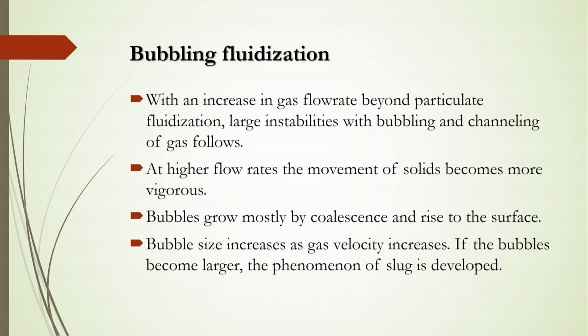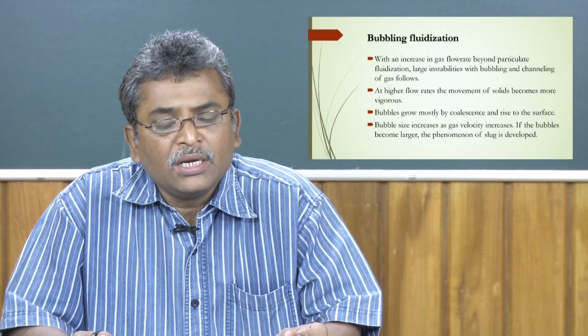Whereas in bubbling fluidization, of course, you have to increase the gas flow rate beyond this particulate fluidized bed, so that you can have large instabilities, or some instabilities, in such a way that there will be a formation of bubbles and channeling of the gas that will flow inside the bed. And at higher flow rates, of course, the movement of the solids becomes more vigorous in that bubbling condition.